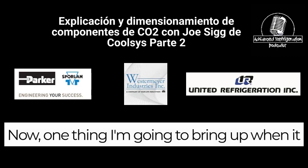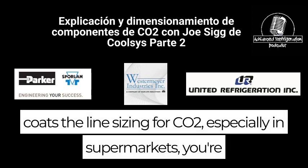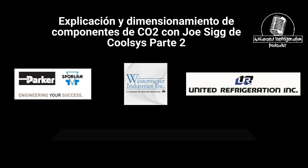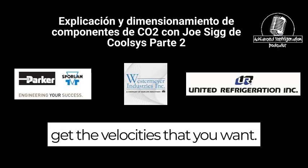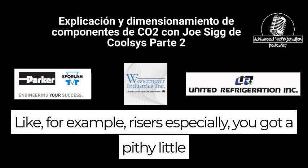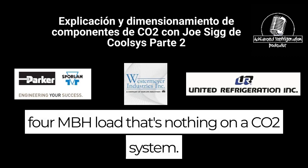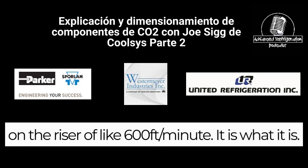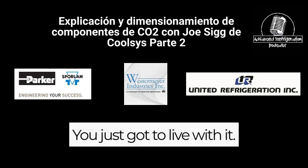So now one thing I'm going to bring up when it comes to line sizing for CO2, especially in supermarkets, you're going to have situations where you have a 2-door case on the end of the lineup. You're not going to be able to get the velocities that you want. You just have to go 3/8-inch piping and live with it. Like, for example, risers especially. You've got a pithy little 4 MBH load. That's nothing on a CO2 system. You're going to end up with velocities on the riser of like 600 feet per minute. It is what it is. You just got to live with it.